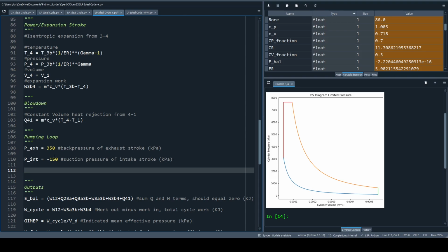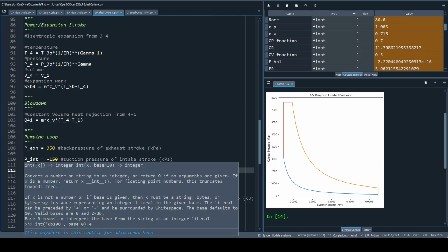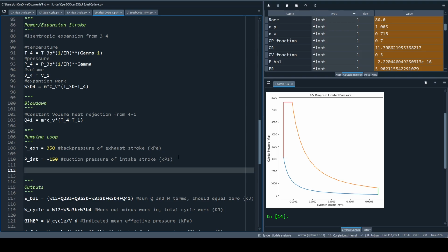So the piston is going to be moving down in the cylinder, and it's pulling against all the restrictions, the valves, the ports, the butterfly valve for the throttle, and basically we're getting a vacuum restriction here. So with these two pressures, we're going to take our PV diagram and add 4 more points. So we have 1, 2, 3 alpha, 3 bravo, and 4. Normally 4 goes back to 1 for blowdown, but now we want 4 to go to 5. And 5 is basically just going to be the cylinder lowering in pressure, partially a blowdown phase here, until it reaches the pressure at the exhaust.